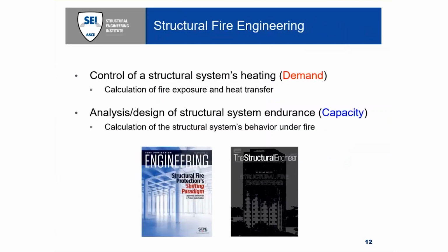As a performance-based alternative to standard fire-resistant design, structural fire engineering aims to control the heating of the structure intelligently, as well as provide adequate structural endurance to satisfy explicit performance objectives. And within this framework, thermally induced forces and degraded material properties due to fire exposure can be limited by the rational and intelligent allocation of structural insulation, control of fuel loads, or other fire exposure mitigation techniques that are passive.